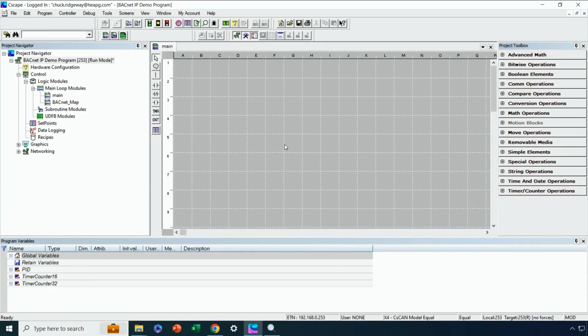Okay, so let's go ahead and test our BACnet IP configuration on our machine so that we're ready to go as soon as the installation occurs. We've got more confidence that everything's going to work the way we anticipate it should. Okay, so we'll just do a really quick review of the BACnet configuration. It's very similar, if not identical, to what I had last week, although last week we were focused on MSTP.